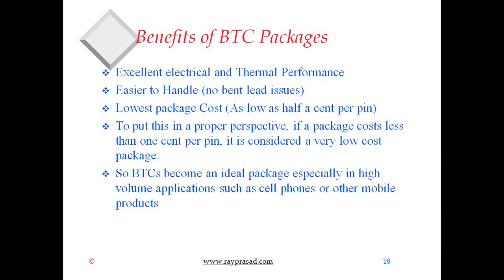That's what the electrical engineers call parasitic loss, which slows down the signal, and that's not the case in BTC. In BTC, you're going to have a much faster connection. Similarly, for thermal cooling, you are directly in contact with the board, so it's going to cool really well.